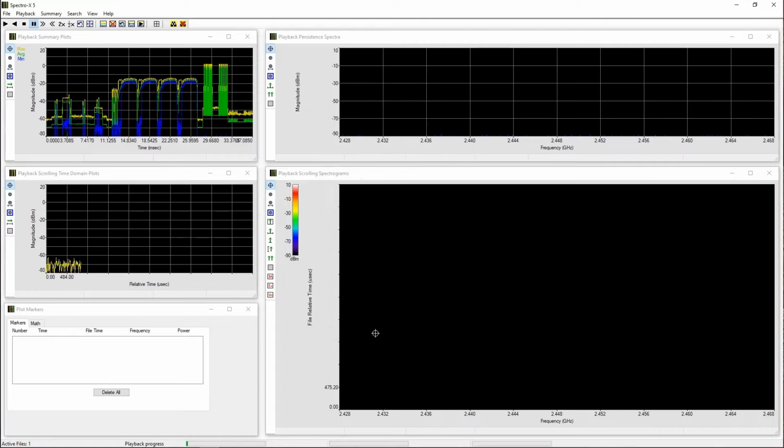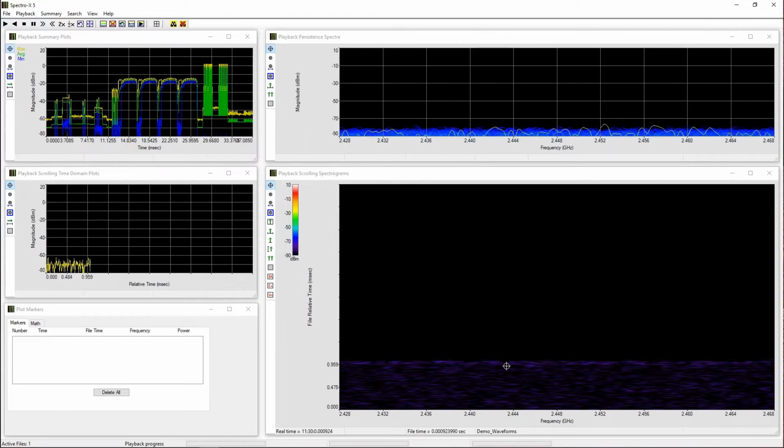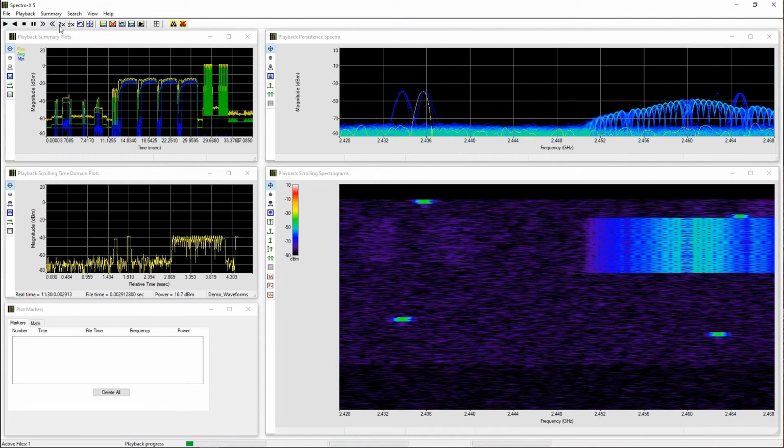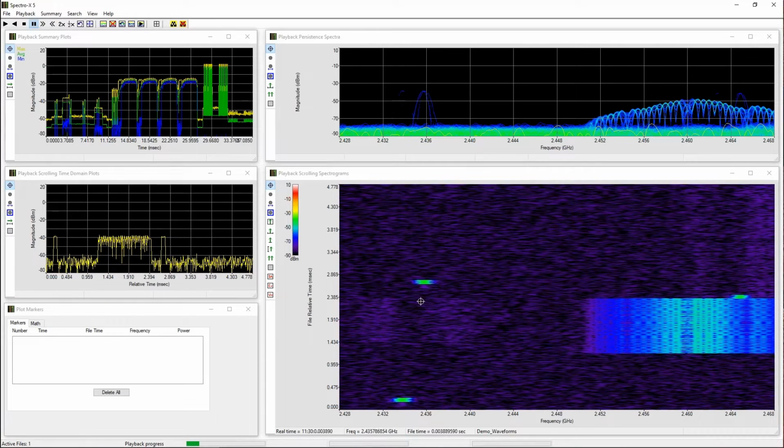Those of you that are familiar, that will change the window size to discern between closely allocated frequency components. As you see here, the view now has quite a bit larger noise floor because we've changed the resolution bandwidth, and these initial chirps in the beginning seem to be more of a continuous signal instead of a bit of a splatter of information.